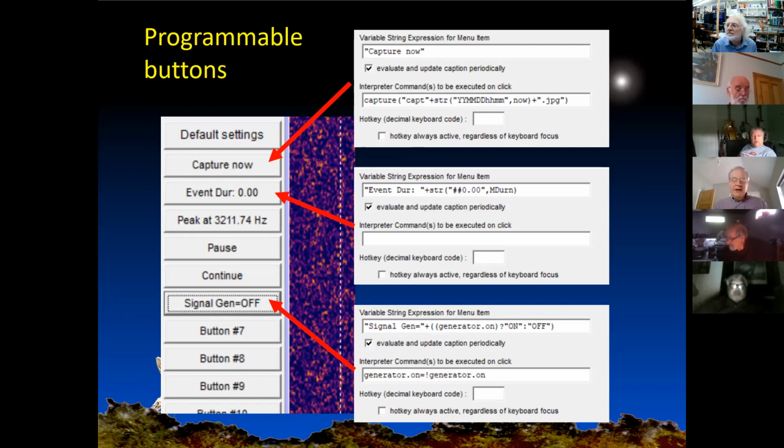So effectively, I can create an artificial meteor, even if I don't have an aerial connected. So that is a very useful test facility if you're getting started, to make sure you're looking in the right place and everything within the laptop or within the computer is working fine. I can also check the event log to see that a test event has been logged there.